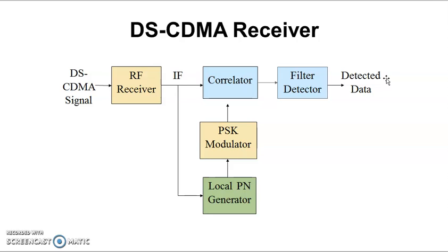We have seen that earlier. When the locally modulated signal is phase synchronized to the received signal, the output signal bandwidth is reduced to the data modulation bandwidth, and the signal passes through this narrowband filter. That happens when the correlation peak occurs, and the output of the filter is modulated data without the PN code, which is detected by the detector following the filter. In that case, the clock generator frequency is fixed at the recovered clock frequency.